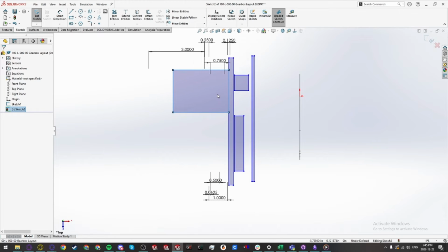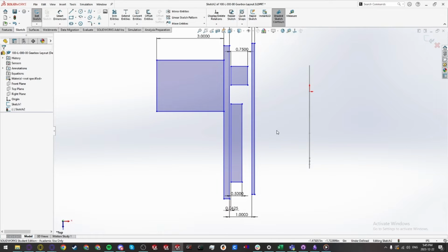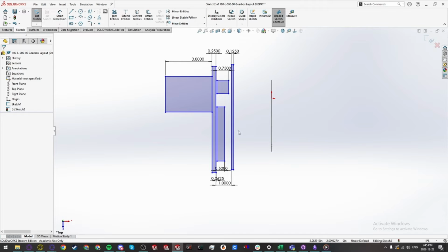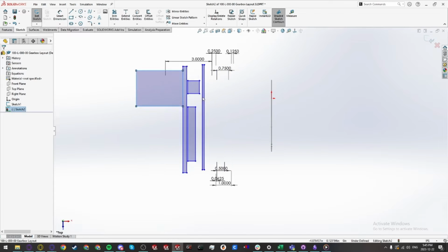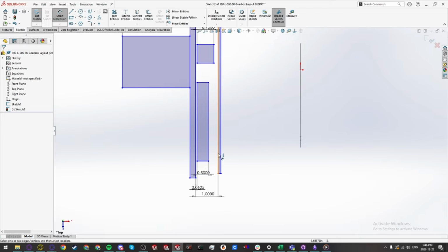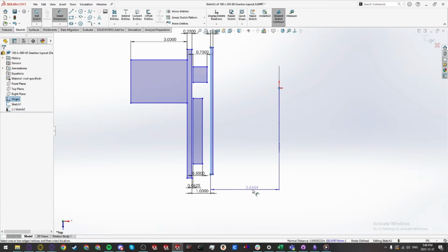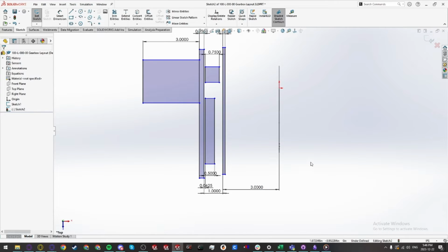So that's kind of everything related in terms of each other. We can also work on just defining everything horizontally because it's still floating around here. Just for the sake of showing off what layout sketches can do and top-down design, I'm gonna define this and say that this interface of the support plate is gonna be 3 inches from the origin. And you'll see everything is now fully defined. Everything doesn't move left and right anymore.